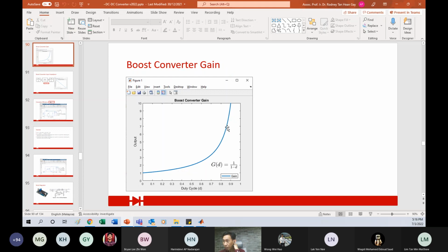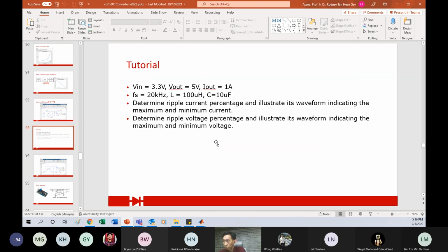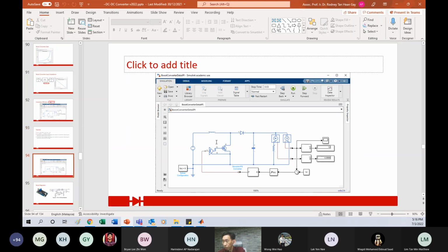Because the PWM becomes so sensitive, especially at 0.9, maybe 0.91 and 0.92, there will be a difference of 10 or 20 watt, so it becomes very difficult to control. That's why it easily goes out of stability. If you don't tune, or you may need a much more advanced type of controller. So usually we design them to operate within the range of 70%.